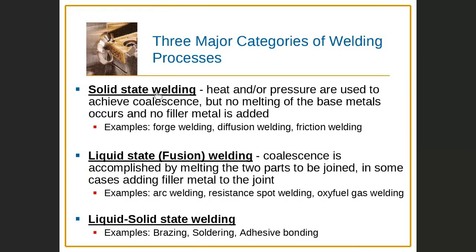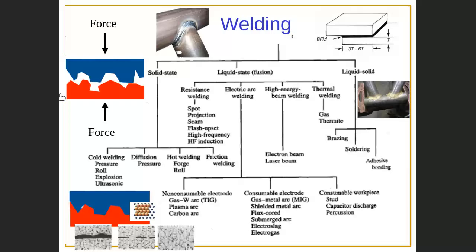Solid state welding. This is explaining solid state welding. Actually, in solid state welding, we apply pressure and leave it for a while. But if you would like to speed up the process, heat the two materials. Why heating? Because it speeds up the migration, since it is mainly related to atomic migration between the two materials.